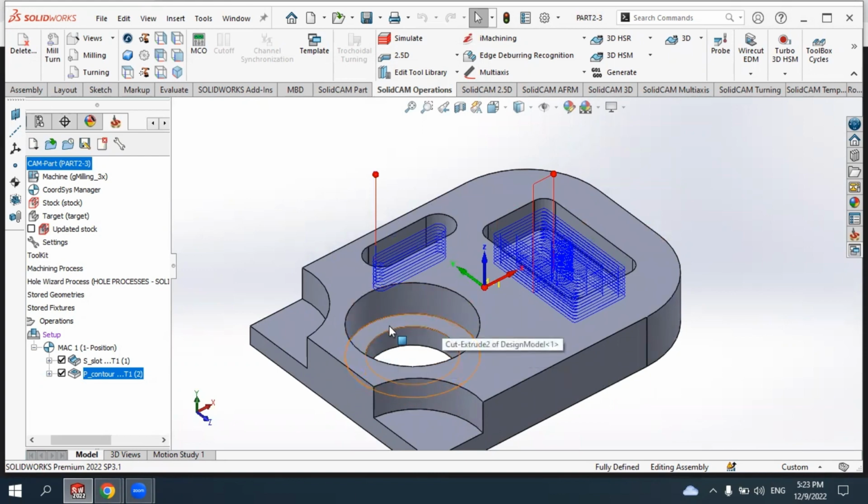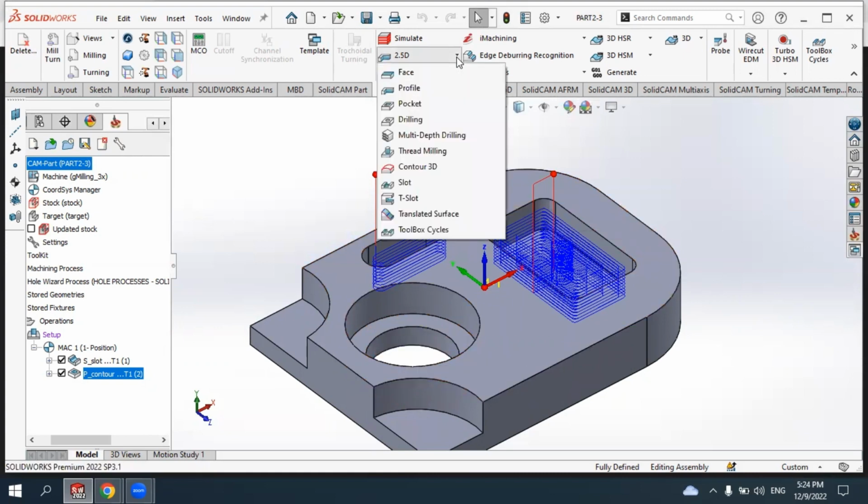In this case, we need to make here the two depths. Firstly, we will remove until this face, this way, then that final face. So we need to make here the two steps. So let's go to the pocket. We can use here again the pocket option.